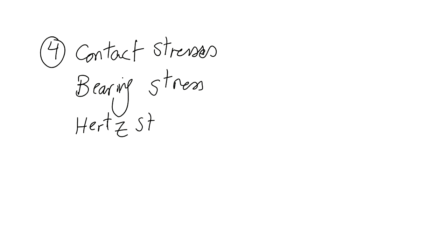Doctor, can we call it crashing stress? No, not crashing, C-R-U-S-H. It leads to crushing because, for example, guys, imagine that you are holding a chalk in your hand and you are pushing this chalk against the blackboard, and you are strong enough, mashallah, to keep pushing until you see that this chalk will get crushed. But mainly it's crushed because of that contact stress. We cannot call it crushing stress or whatever you said before. You got it, man? Yes, doctor.